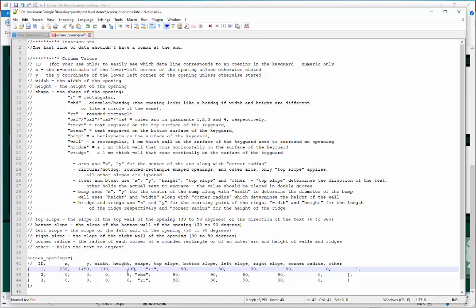But they are nice and square, so we'll keep them square. And I've already got rounded rectangle as the top, or as the shape type. What I think I'll do here is I do want to provide some amount of slope down. Let's experiment just by putting a 60 in here, because that's what we often use on the cell openings in the grid.